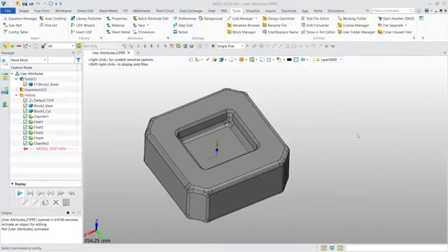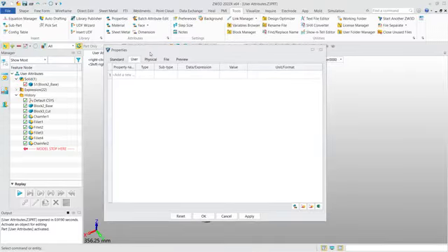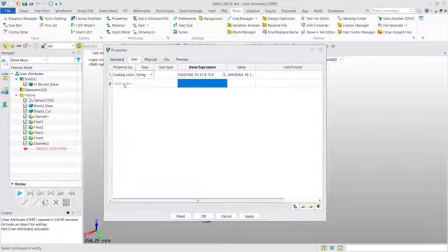Okay, for user attribute, we can also access it in the tool tab property command. And here you can see a user attribute. And as I said before, we can add common string to it, like coating color. And for the type, you can see string, bool, integer, number, and even date. So here we need the string. And then we can type the string directly. I can already copy one. Okay. And you can add more to it, like version